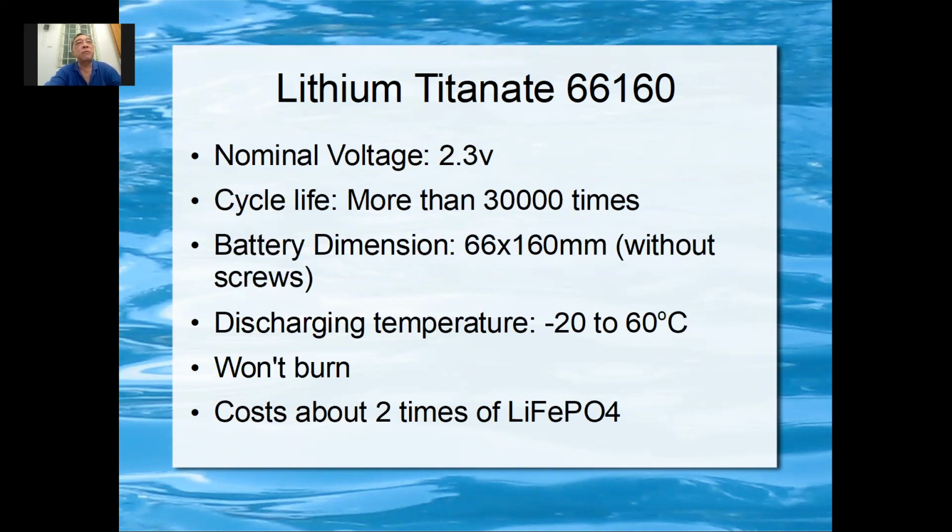Lithium titanate is normally used only in a battery pack. If you want to build a battery pack, let's say 48 volt, 24 volt, a huge battery pack, let's say a 40 kg battery pack, then you can use lithium titanate. Okay, and the good thing is it has a cycle life of 30,000 times.